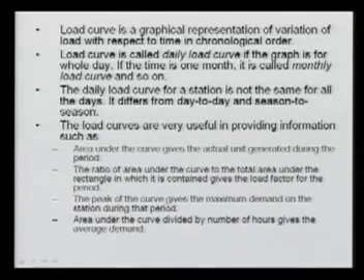The daily load curve for a station is not the same for all the days. It differs from day to day and season to season. So normally for analysis purposes, we always go for the various seasons like summer, winter or monsoon season, and based on that we analyze. Load curves are very useful in providing information such as the area under the load curve, which gives the actual units generated during that period.